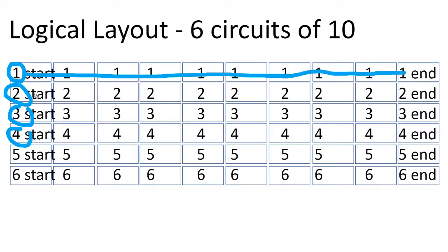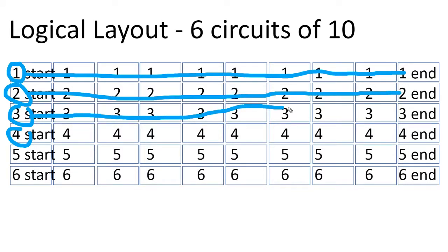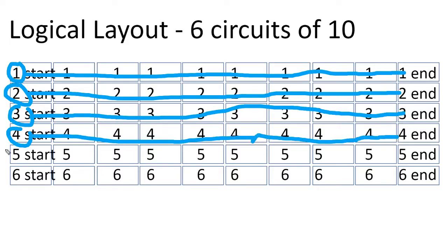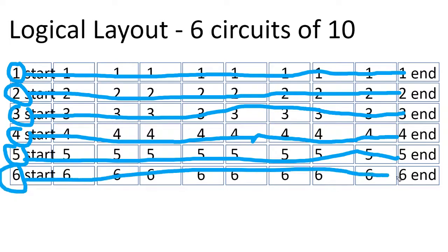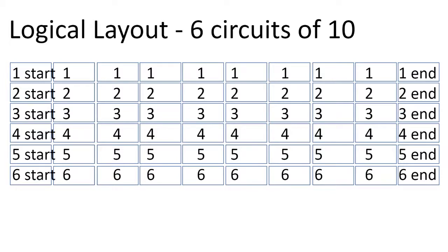There are two approaches to circuit layout. I think it's best to go for a simple, logical circuit layout, even if it means using more circuits than necessary on the roof if those circuits start and stop in logical places. For example, starting a circuit on one side of the array perimeter and ending the circuit on the opposite side, moving across the solar array in a straight line, is a logical, straightforward circuit layout.